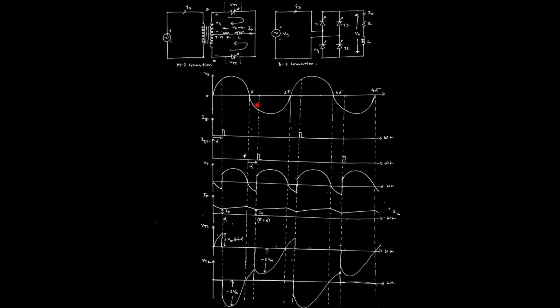When the supply voltage goes negative, the inductor tries to discharge, and the charging and discharging currents are both in the same direction. So even though, due to the negative half of the supply, the thyristor is in negative biasing condition, the stored energy in the inductor tries to discharge in the same direction as before.